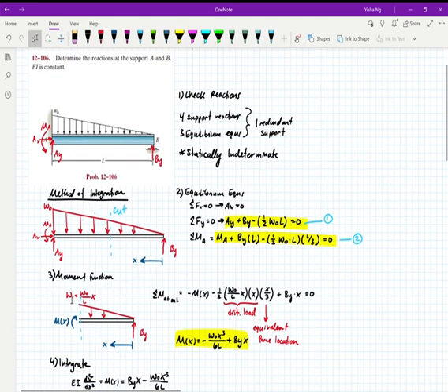So the first thing I've done is I've calculated what W will be, right? Because your W naught only applies at this top point of your triangle. So if you cut your triangle, you have to find the new W value. And that's going to be your slope, which is W naught over L, multiplied by X, which is whatever distance you're making the cut at.